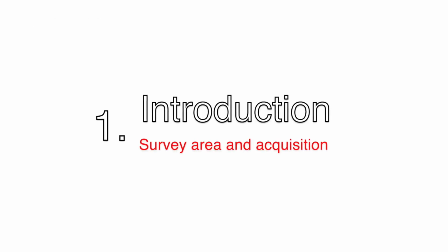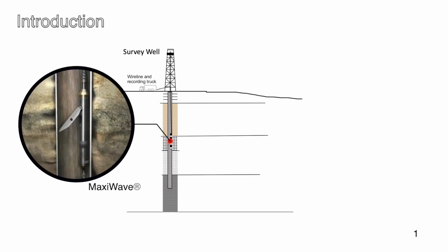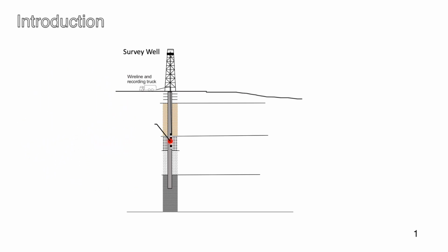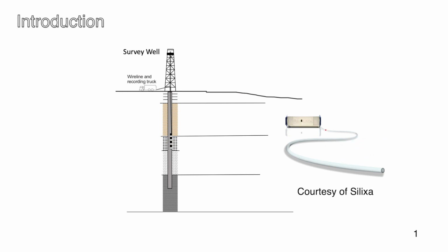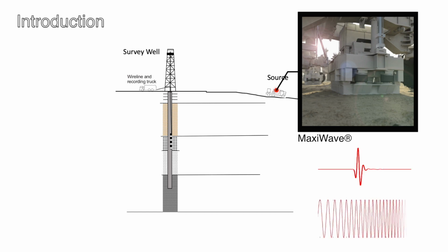Let's first revisit the vertical seismic profile survey geometry. VSP surveys employ surface sources and borehole receivers and record high-quality multi-component wave fields. The receivers are often 3-component geophones that are clamped onto the wellbore while recording. Recently, optic fibers have become a cheaper alternative sensor and have considerable potential for permanent monitoring. The sources can be either dynamite or vibroseis trucks. The dynamite generates an impulsive source signature, while the vibroseis truck generates a sweep of vibration with varying frequencies.